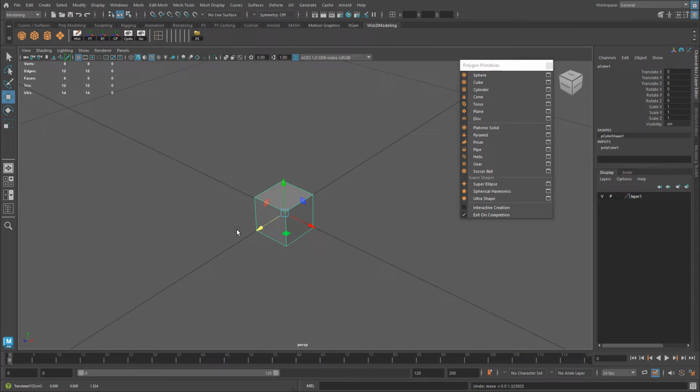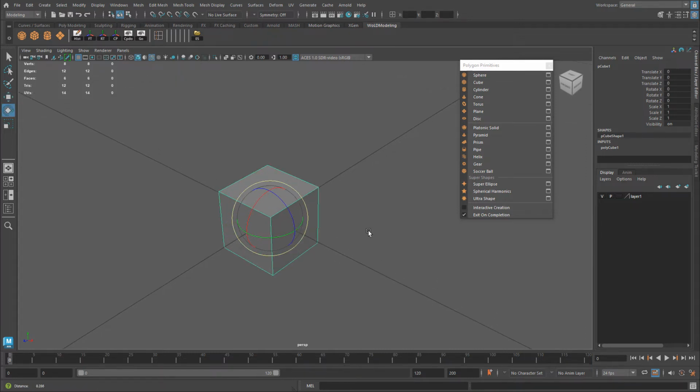Then if you switch over to rotate, E, you can rotate your object. You have the same kind of gizmos right here. So you left click, hold, and drag to rotate on each of these, depending on how you want to rotate the object. On X, Y, or Z. And then you have scale. If you hit R, switch over to scale. You can scale the object on X, on Y, on Z, or all together uniformly on X, Y, and Z together.